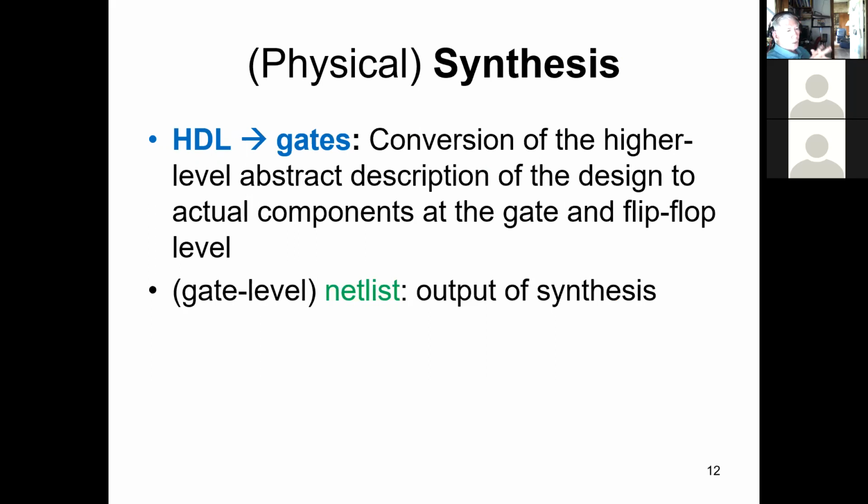When the router routes your project on, say, an FPGA, we have these big interconnect matrices going from slice to slice of the chip in the case of Xilinx, and it may route your signal very circuitously in such a way that there's actually something approaching a nanosecond or so of timing changes, and this can cause problems.